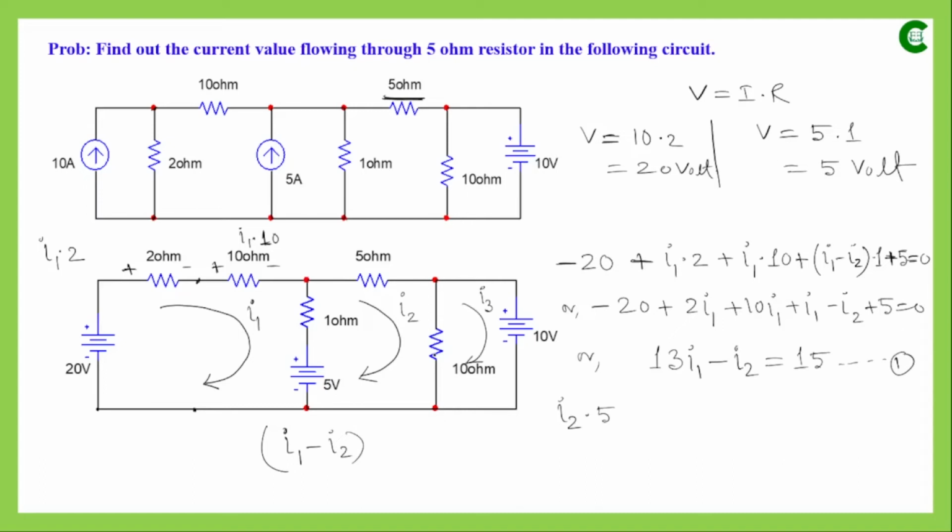Again this is a resistance which is common between these two loops, and we can see easily that through this 10 ohm resistance, the I2 current is flowing in the downward direction and the I3 current is flowing in the upward direction. So the net current through this 10 ohm resistance will not be only I2 or I3, it will be the net value of I2 and I3.